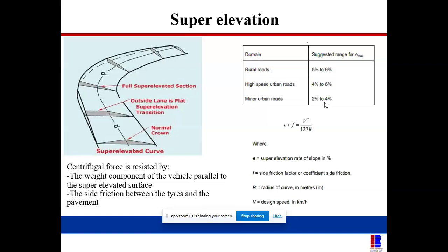Now increase the curve. But just like I explained earlier, if it's a built-up area, and you're having that curve between two, and the built-up area is close to the road, and the government or the agency says they're not ready to pay for compensation, so you just find a way to navigate around the road along that curve. Once I'm done with the design, we provide road signage on our drawings. So you provide the starting point of the road, and the signage will be there to caution the driver of the maximum design speed of 60 kilometers per hour.